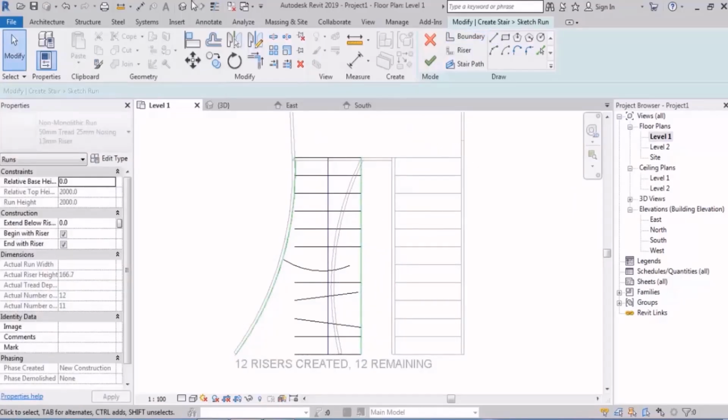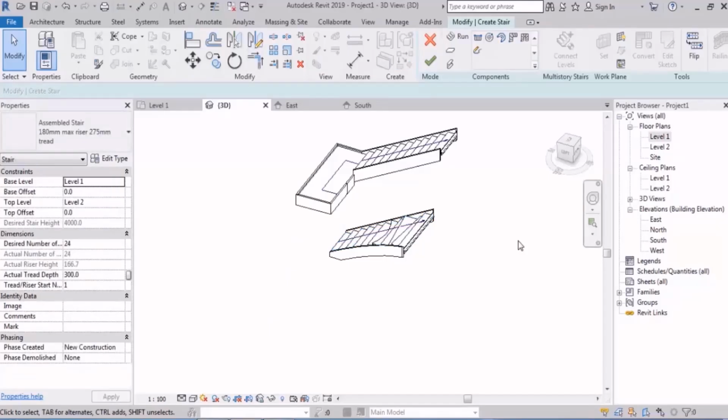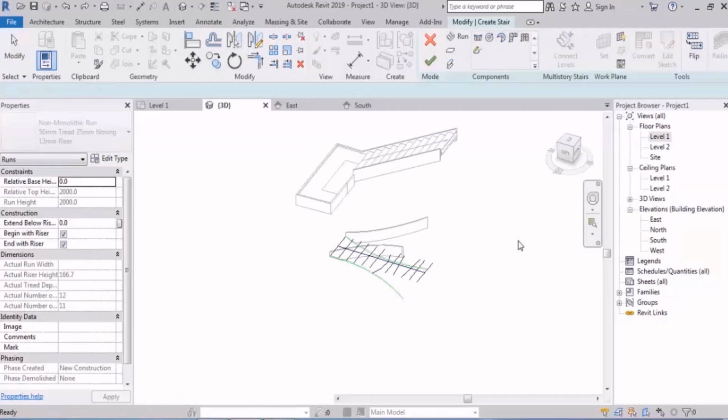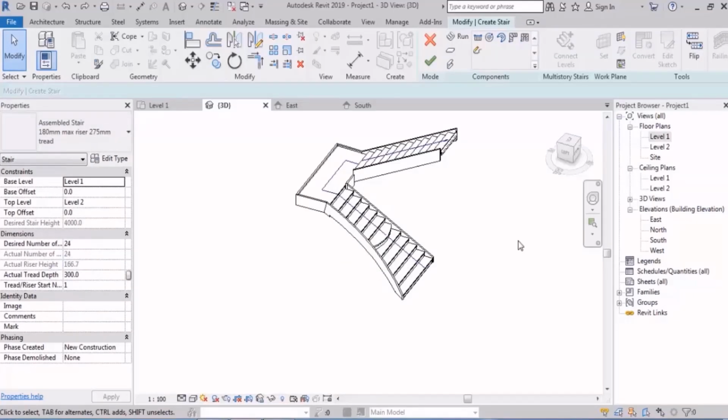I say that I'm sorry, I draw it back again, the same way. But would it be alright? No. There is only one way, and that's to undo. You see, you must click on undo until it gets correct. Now a point. While you're editing your stair, at every level, you need to click on that check to make sure things you have done so far have been accepted by Revit or not.